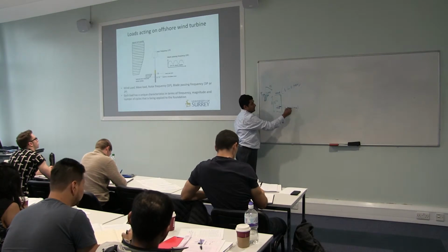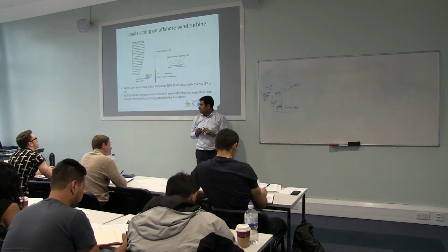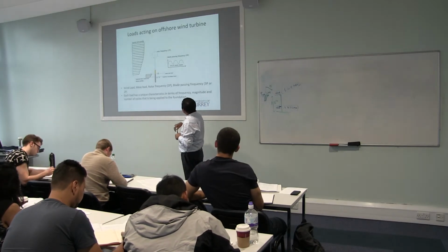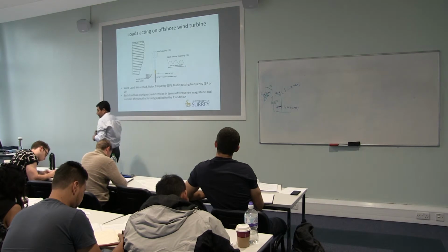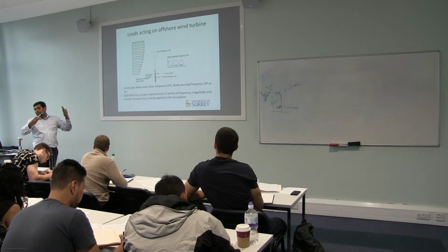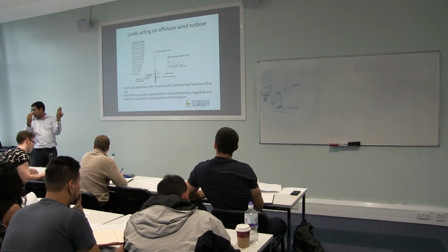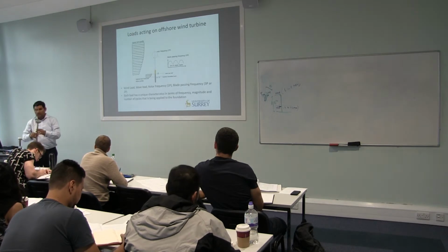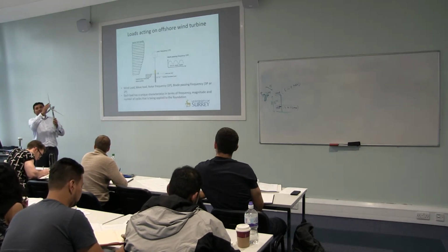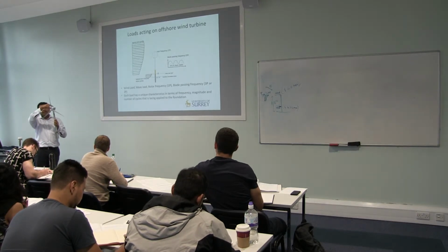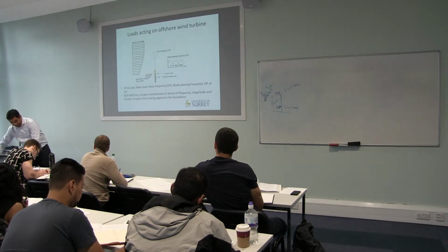Meganewton of load. The massive load acting, right? Then there are loads due to the rotor. If the three blades are not pitched accurately, there can be a load due to the asymmetry. Say, for example, these three masses are not the same, there is a small difference, that will cause a wobble. That wobble will give you a small load at the top. That is the 1P loading.